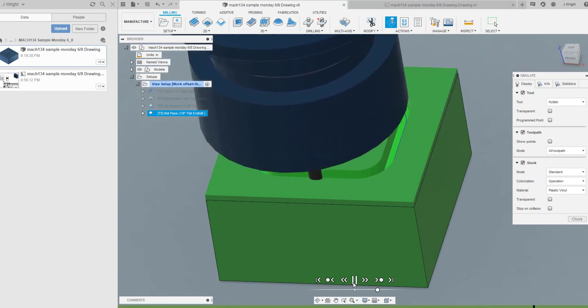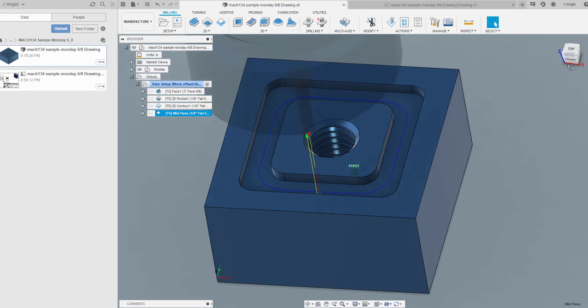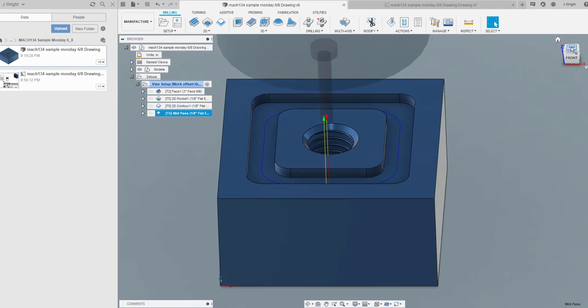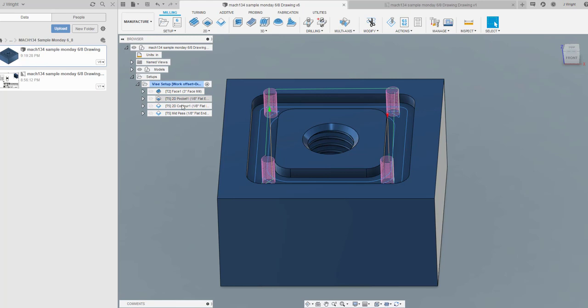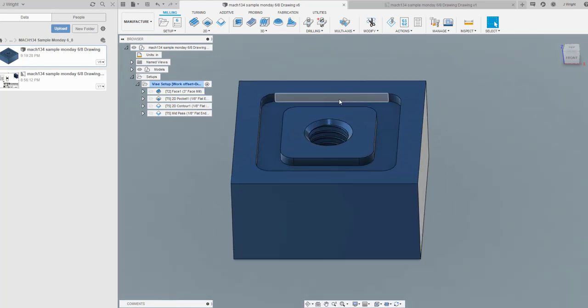It's kind of hard to see there. This is the entrance and exit of it. It spirals in and out, but it still stays within the boundary. See? Like if I was using this as a tool 6 and then these two as tool 7s, I might do something like this. If I'm doing it the way I'm doing it now with tool 5, I'd probably leave it alone. So here takes care of this. The only thing that we have left to do is tap the hole in the middle.